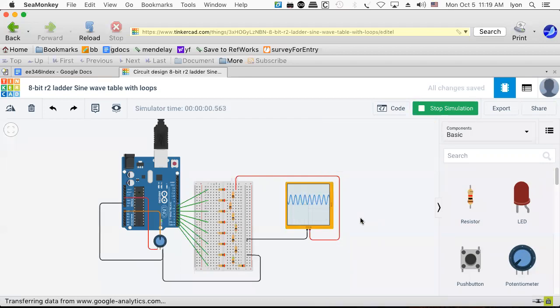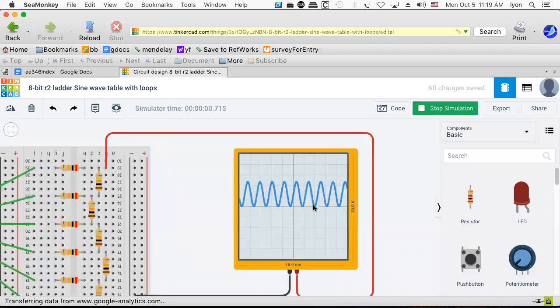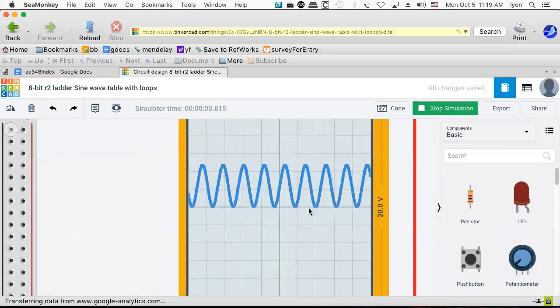real, that's really 1 millisecond, then in theory, you can look at this waveform here, and you can say, hey, wait a minute. Here's a trough, and there's a trough. This is 1 millisecond per division. So this is a little bit lower than a kilohertz, right? Because 1 millisecond is 1/1000th of a second.